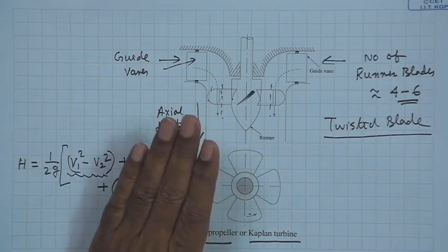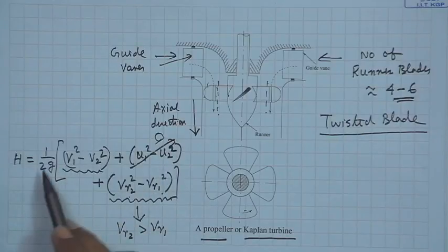There are machines which are axial flow but impulse. For axial flow reaction machines, the flow passage is a converging type, that means the cross sectional area perpendicular to the direction of the flow, in this case the axial direction, is reduced to increase the relative velocity to get a drop in the static pressure or static head of the fluid in the runner. So, this has to be also kept in mind.